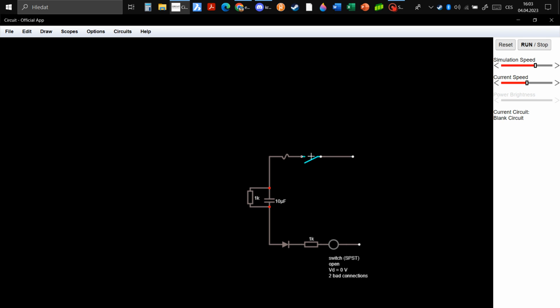And how is it working? Simple. When you turn the switch on, it goes through the fuse, then goes into the capacitor, which does the power factor correction. These ones are hoping that you have an inductive load. Next, you've got a discharge resistor to discharge it so it doesn't give you a zing when you unplug it. Then this is just the circuit for powering the LED: a rectification diode, resistor, and the LED.